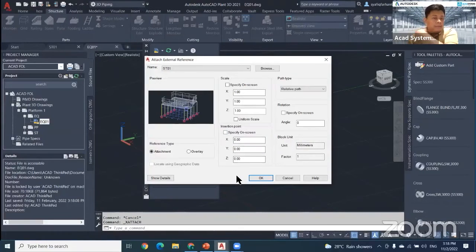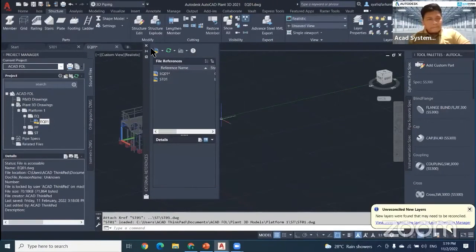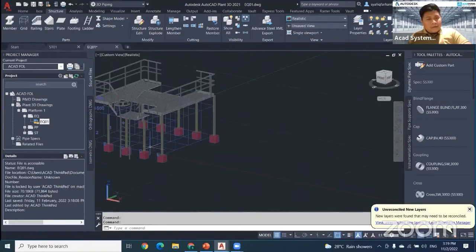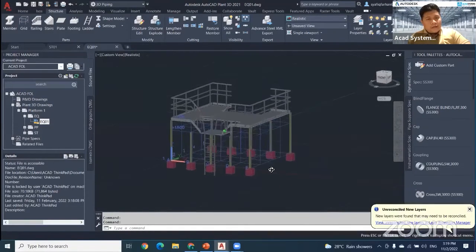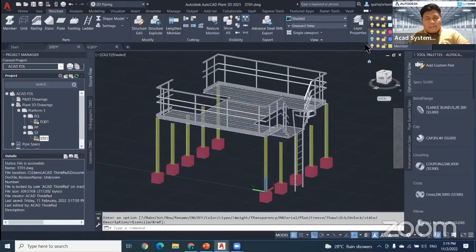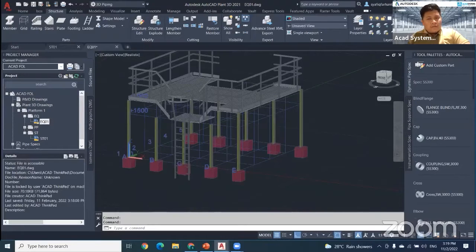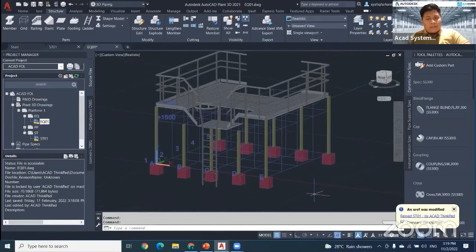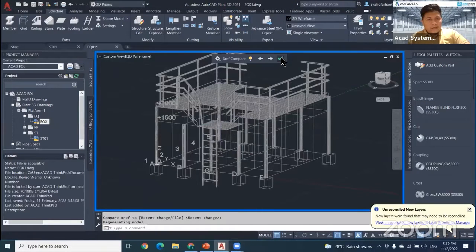If you want to make it in a proper coordinate, when you create a structure, you just need to insert the grids at a proper coordinate directly. So that will be the idea. Then hit OK. Okay, my structure over here is done. I want to hide the grid, so go back to my structure drawing, click grids, hide this one, and then click save again. With this extract, when I go back to my original equipment file, I can reload my structure, which already has the grid removed.